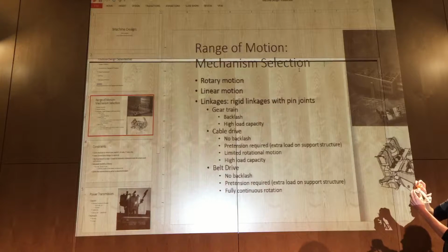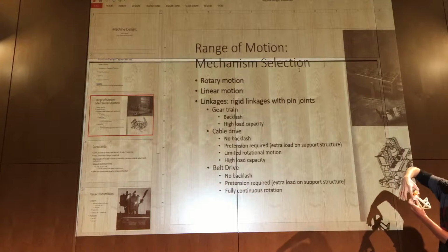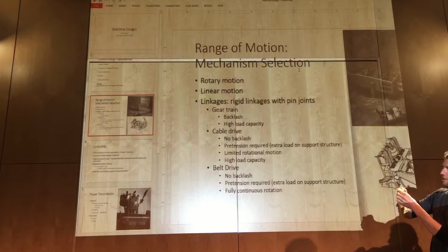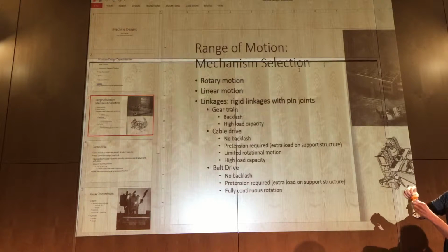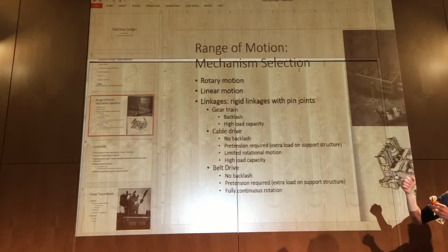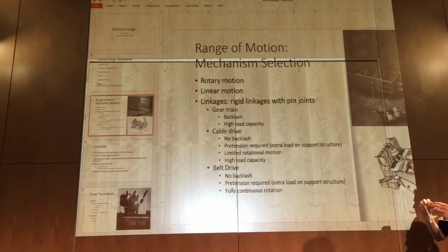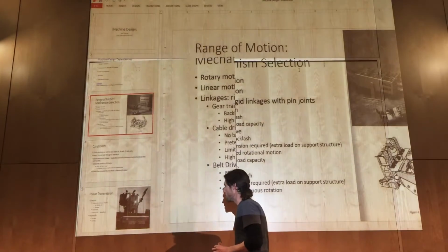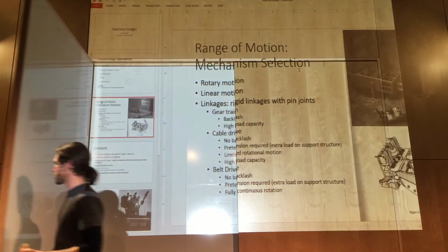So as one of these rotates, that point is essentially just sliding along the tangent and sliding along the other side, and that's what keeps your orientation. You want the belt to be non-extensible, just like a linkage would be, like it's a piece of metal hanging on there. And in fact, the load member inside of the belt is actually fiberglass or Kevlar if you have fancy ones.